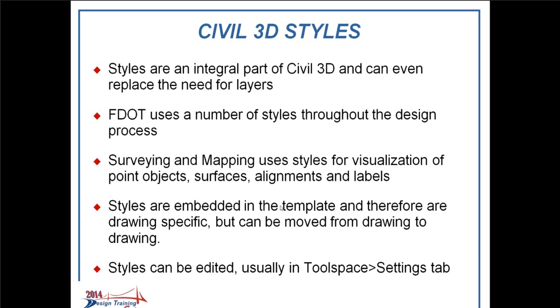They can be moved from drawing to drawing, but the way FDOT has set these up, we've set up these templates for surveying and for all disciplines for that matter. And in our surveying templates, we have specific styles that have been set. They can be edited if need be, and usually that's through the tool space settings tab.